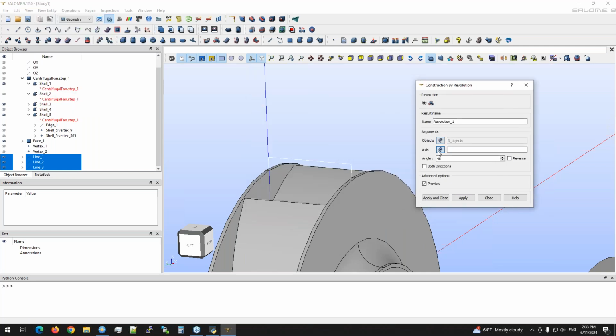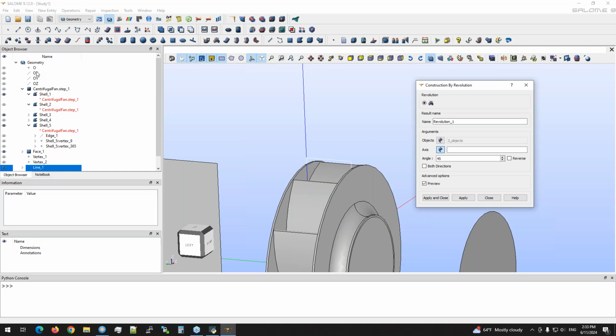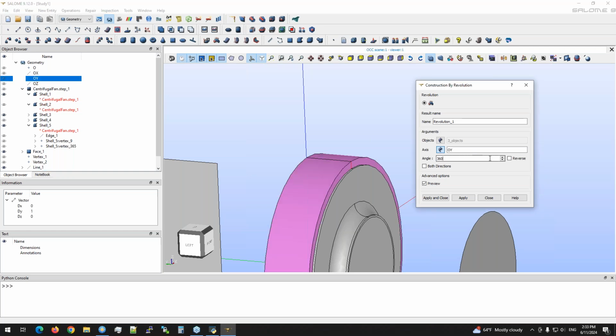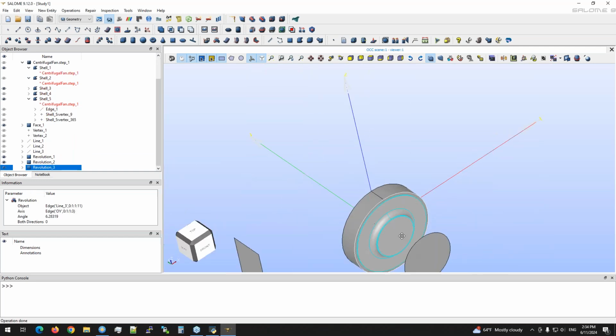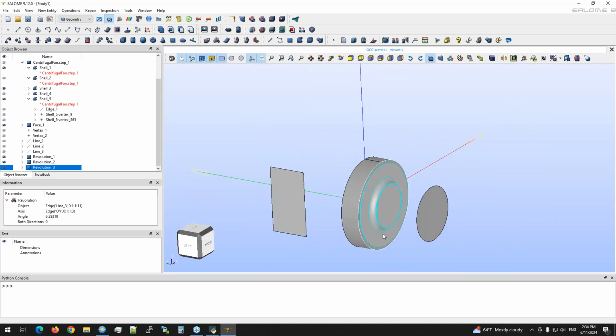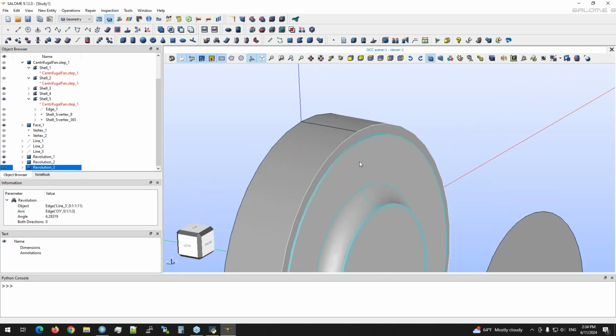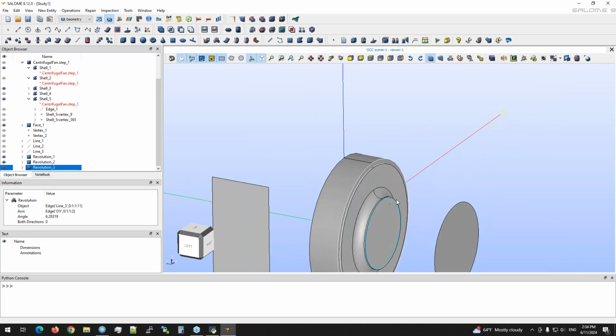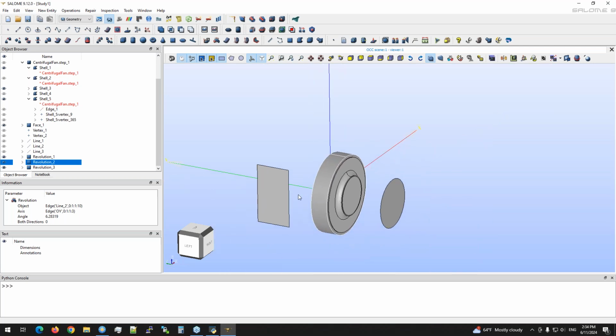Nice. So here I will set the axis. The axis of rotation is the y-axis, and I would like to rotate it by 360 degrees to create a full interface for the full wheel geometry. All right, so this is the one option, I think the most suggested one to do. And now we have defined a domain for the impeller itself, which divides the inlet suction part and the volute part from the rotor.